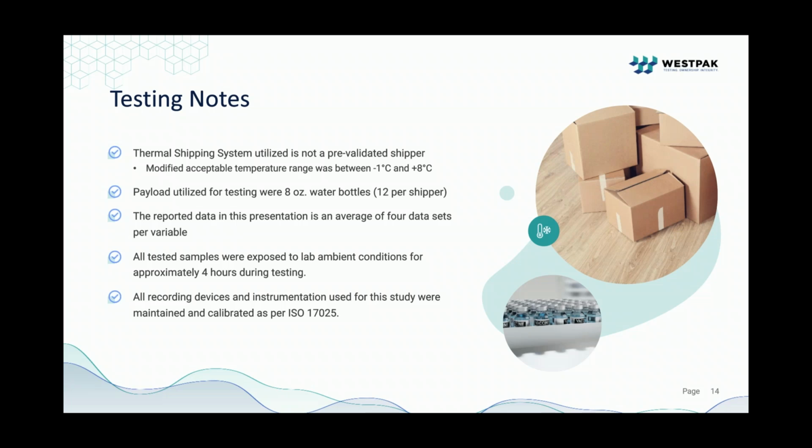To keep our variable cases as controlled as we could, all test samples were exposed to lab ambient conditions for 4 hours after the preconditioning. No matter what type of variable case we were testing, we limited the variability by keeping them outside of the chamber for 4 hours. And, of course, like all testing done at WESTPAK, all our devices and instrumentation are maintained and calibrated per ISO 17025.